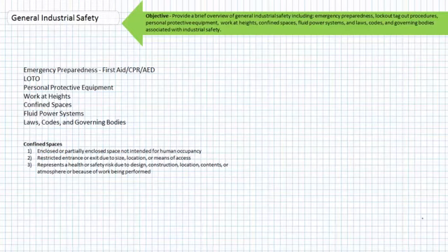All of these environments will require special safety consideration, attendance, clear and constant communication channels, and special equipment to extract an injured worker from the confined space should it become necessary. Confined space injuries are often multi-fatality events because the natural inclination is to rush in and attempt to save someone. Environmental hazards such as low oxygen or the presence of an invisible poisonous gas must be tested before entering any confined space. You cannot help a casualty by becoming a casualty yourself.